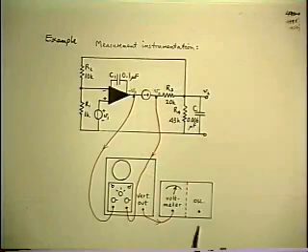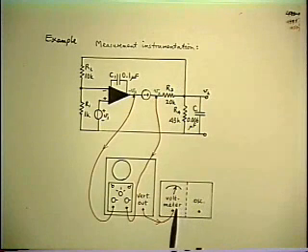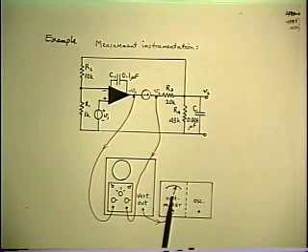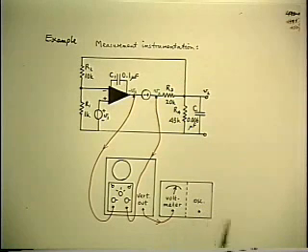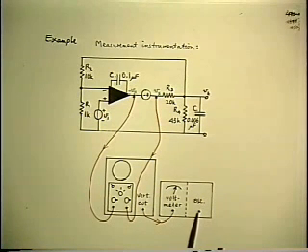Narrowband voltmeters are available as part of boxes known as wave analyzers or network analyzers. And a fairly low-cost one that I've used for a long time is a wave analyzer. Hewlett-Packard makes one, and it combines two functions. A voltmeter that has a narrow band in which the narrow band automatically tracks the frequency of a built-in signal generator or oscillator. So you don't have to worry about tracking the narrow bandwidth. It automatically follows the oscillator, and if you use that as a test signal, then the voltmeter automatically tracks it, and you can get a very wide dynamic range that way.